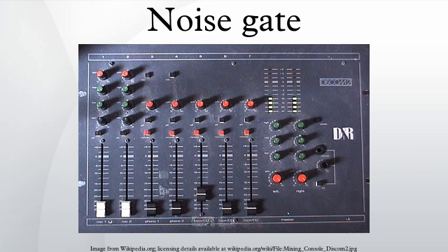In most multi-mic drum recordings, one microphone will be used to capture the snare drum sound and another to capture the kick drum sound. The snare microphone will output a signal composed of a high-level snare signal and a lower-level kick drum signal. If the threshold level of the noise gate is set correctly, a snare drum signal can be isolated. To fully isolate the snare drum signal, the release rate has to be quite fast, which can cause the tail end of the snare sound to be chopped off.